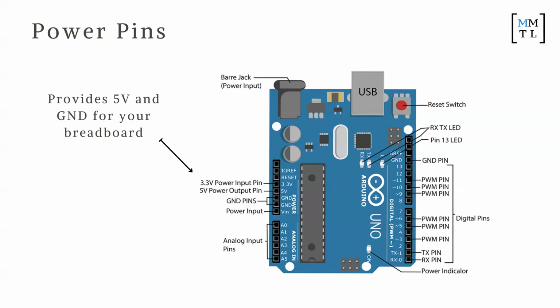Okay, so let's explain a little bit of the logic behind the breadboard, right? So now that I've connected this to 5 volts, if I put it on this row here, which is row 30, then row 30 now operates at 5 volts. Does that make sense? If I connect the Arduino to this, and this is 5 volts, and I connect it to row 30, then row 30 is now 5 volts. If I shift this here to 0, then it's now operating at 0 volts.